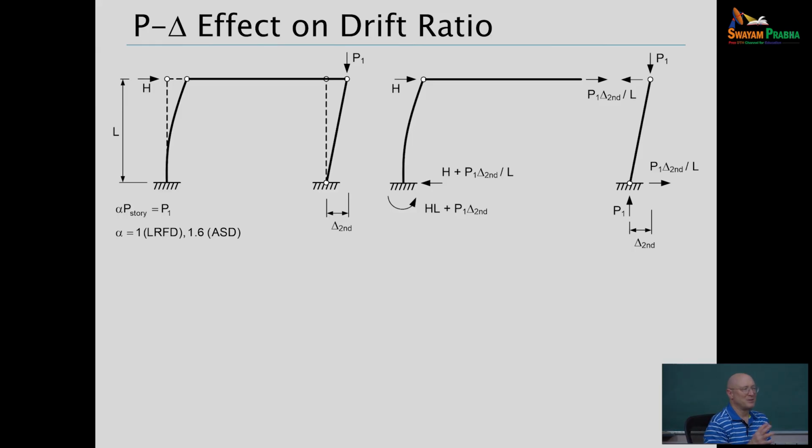And the clever solution was that, well, just take the LRFD load combinations, divide by 1.5, and adopt those as the ASD load combinations. Well, in ASCE 7, we have a 1.4 times dead load. Divide that by 1.5, and you've got a load factor less than 1. So some engineers look at that and worry. Oh, and you've got a resistance factor on the other side. It's okay. And then 1.2 dead plus 1.6 live, divide that.